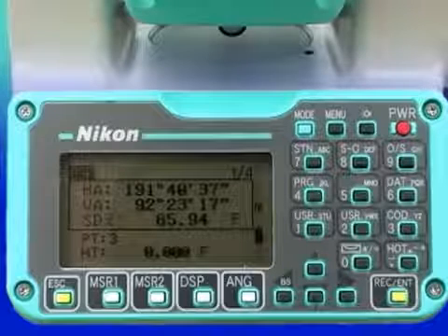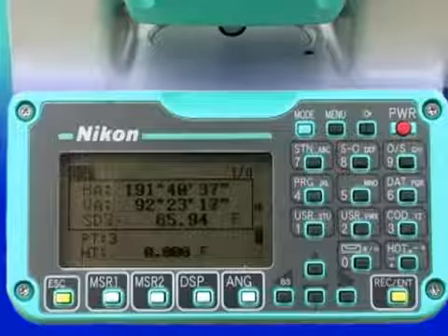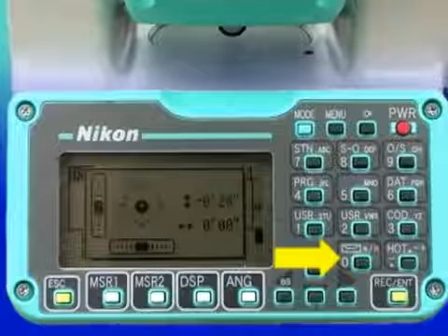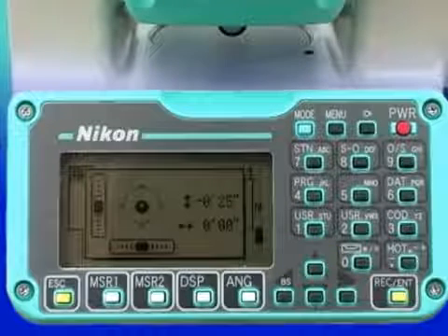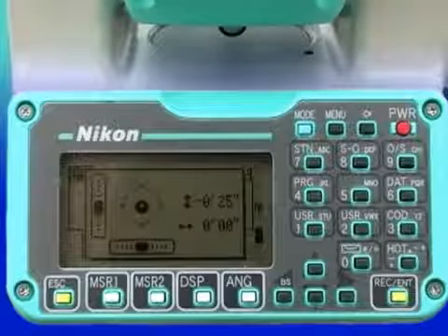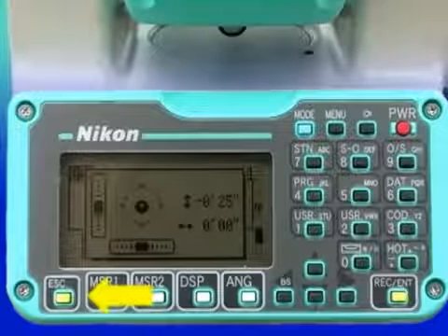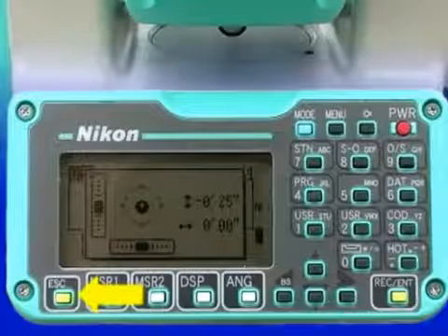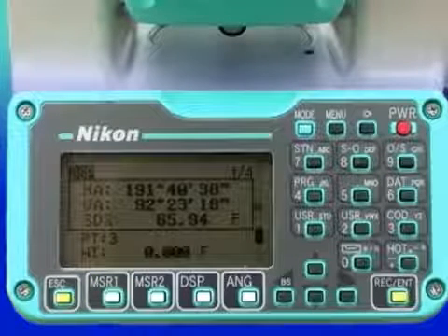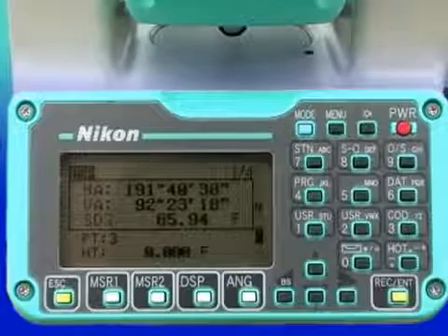In the event that the instrument gets bumped, moved, or otherwise compromised, the out-of-level screen will display. This screen can also be accessed by pressing the 0 key on the numeric pad. Fine leveling is done using the 3 leveling screws under the leveling plate. Again, return to the BMS screen by using the Escape key and tilt the telescope to establish the 0 zenith vertical angle. Remember that the angles will likely have changed as a result of being out of level.